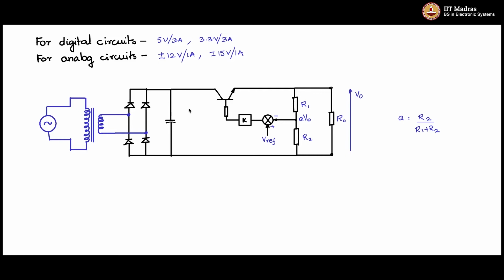So you know that here the voltage is a DC voltage but has a ripple content, has a high ripple content, and we need this series pass to drop all the ripple contents across it in such a way that V0 is kept constant. So this is how this operates. Now, how do you make V0 here match with V reference? How to make the error 0? So if I write this error, and this I will call the base voltage VB,